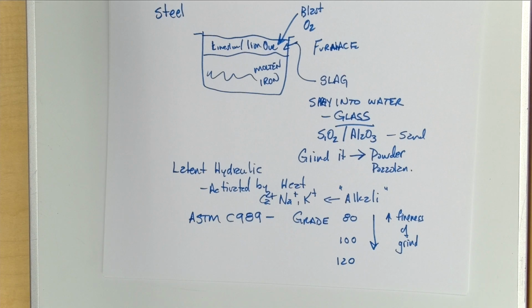Okay, famous story. A lot of granular blast furnace slag made in Canada. They also on the lake in Hamilton have a lot of steel plants, and so as a result, when they built the Canadian Embassy in Washington, they said, let's make it really brilliant white. Best way to do that is lots and lots of slag. So they stripped off the forms, and then they sealed the concrete surface, which prevented oxygen from getting at the surface.